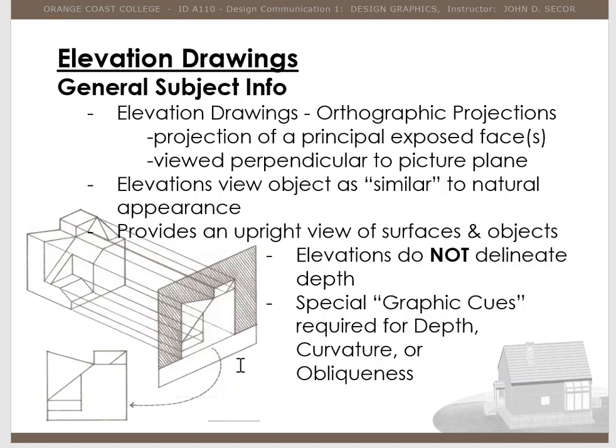So elevations do not delineate. It's hard to tell depth. They do not show depth. So we have to do things to give graphic cues of depth when we are creating interior and exterior elevations. We have to create some interest, and how that's done is through different line weights and material hatches that we use.